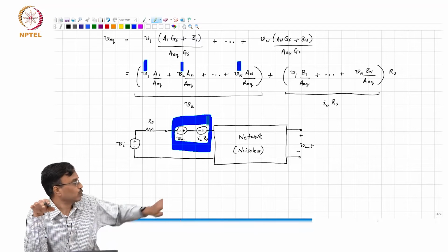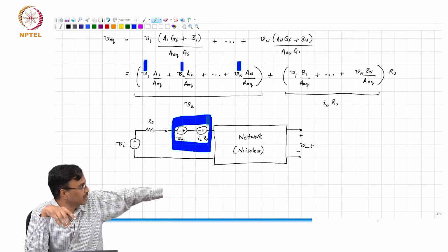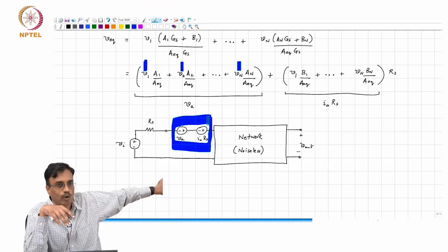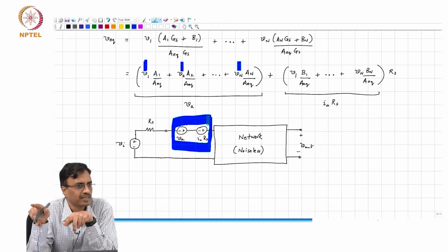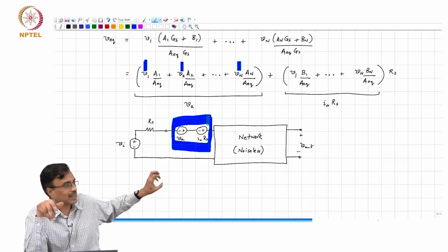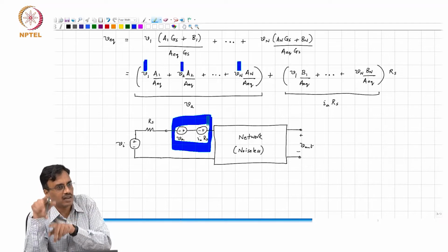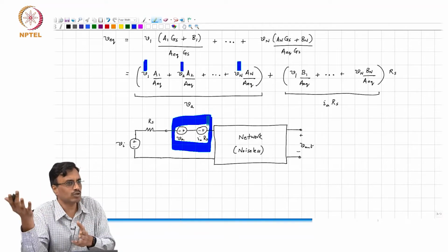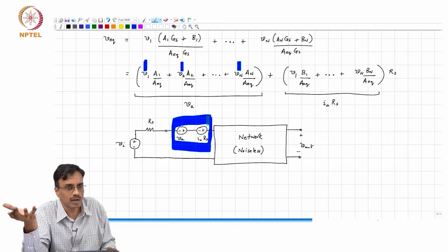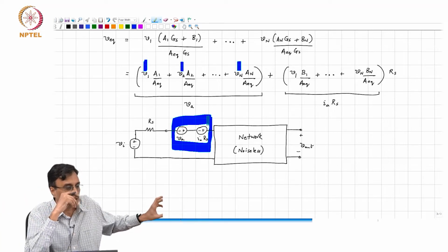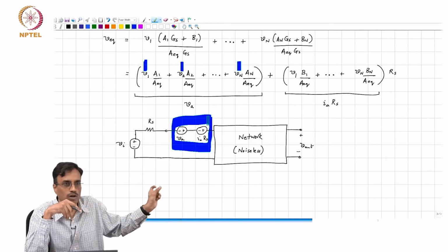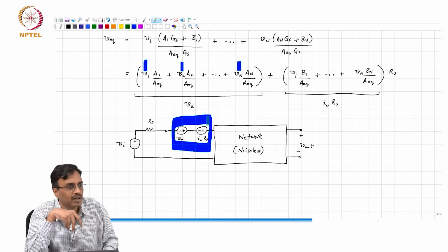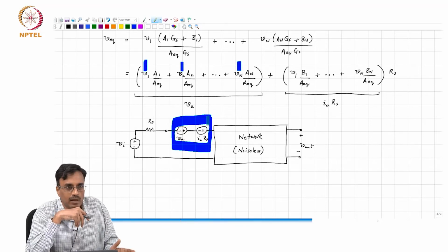If you remove the input source and Rs altogether, the internal sources will cause some noise at the output, correct? But as Rs becomes larger and larger, the noise caused by the internal sources remains largely the same at the output, right? However, the transfer function from Vi, which is also the transfer function from that equivalent noise voltage source, keeps dropping, correct?